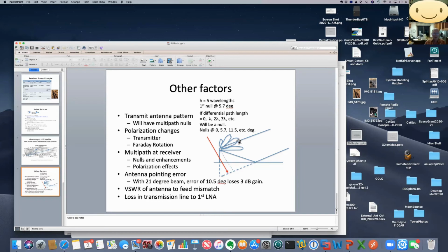So you might say, well, if I have a null, I'll lose 10% of my data. Do I want it so bad that I want to retransmit that data? Or am I willing to say, I'd rather have the current data and not bother with the retransmission? Quite often, for telemetry data, it's okay to say, here's some good data. I have 9 seconds of good data. Here's a second of data loss. Here's another 9 seconds of good data.